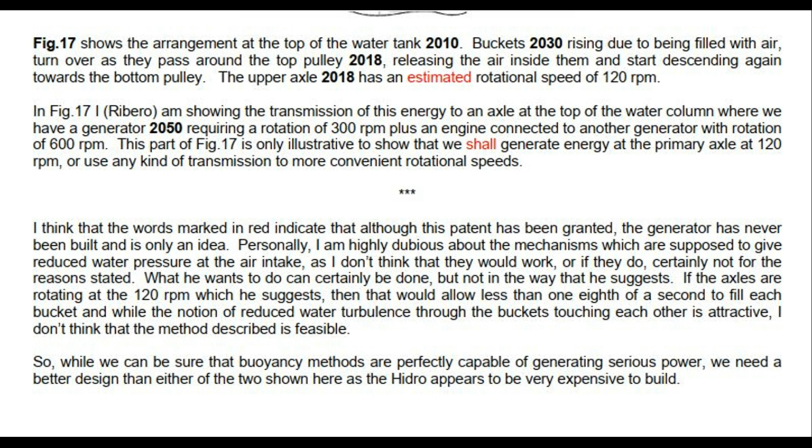If the axles are rotating at the 120 rpm which he suggests, then that would allow less than 1/8 of a second to fill each bucket, and while the notion of reduced water turbulence through the buckets touching each other is attractive, I don't think that the method described is feasible. So, while we can be sure that buoyancy methods are perfectly capable of generating serious power, we need a better design than either of the two shown here, as the hydro appears to be very expensive to build.